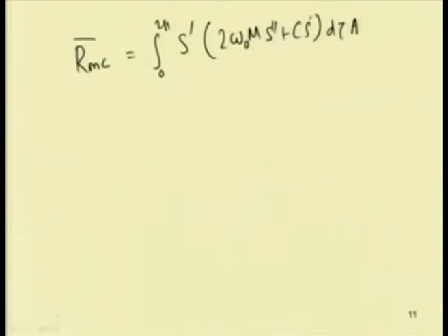So, the solution process begins with a guess solution and the nonlinear frequency amplitude response curve is obtained by solving point by point, incrementing either the frequency or the amplitude, or one can increment both the amplitude and the frequency. In this case one may use this Newton-Raphson iterative method to solve this equation.